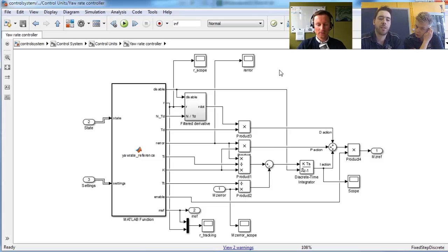Usually you would enable anti-wind-up in the PID block, but it can only use fixed limits. While in our case, of course, the grip varies all the time, so a fixed limit is not really realistic. So that's why we built our own anti-wind-up.